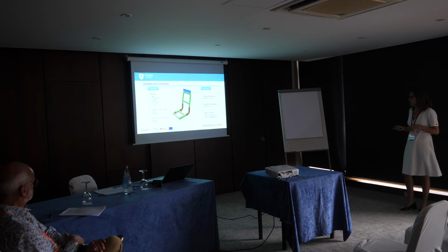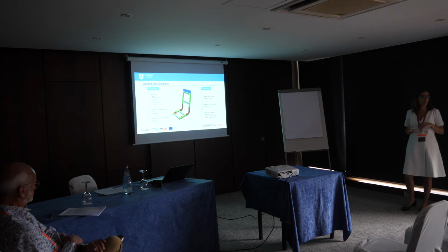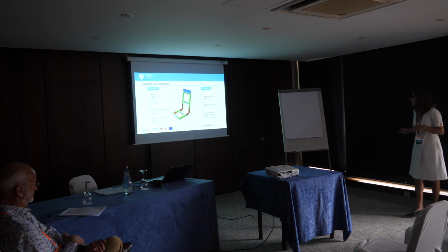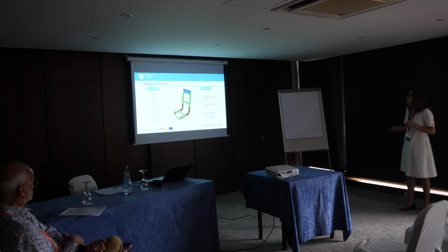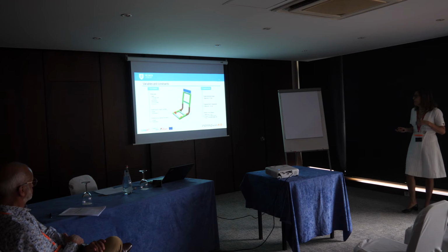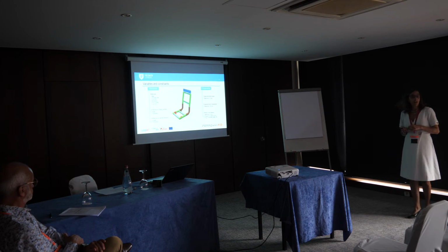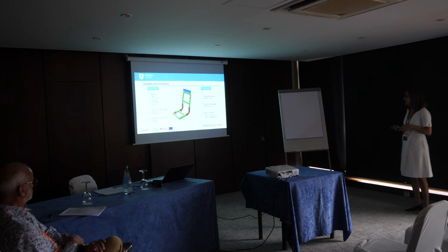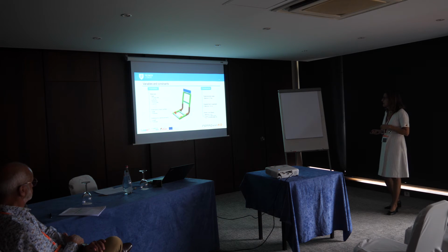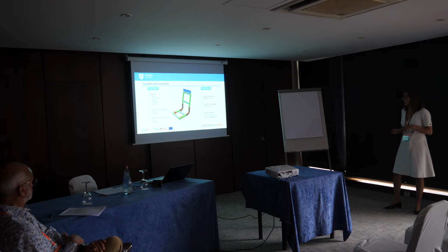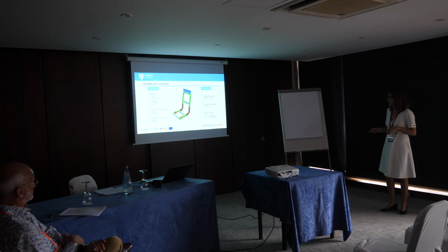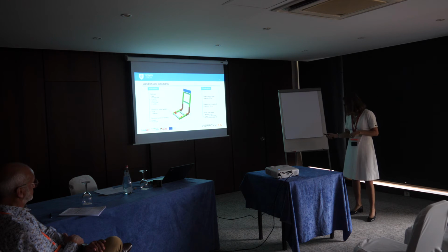In terms of the constraints, and this is very, very important, we define a total mass for the structure of 5.5 kilograms, a maximum displacement of 35 millimeters, and a maximum value for the stress of 60% of the yield stress, namely for the steel and for the aluminum alloy.